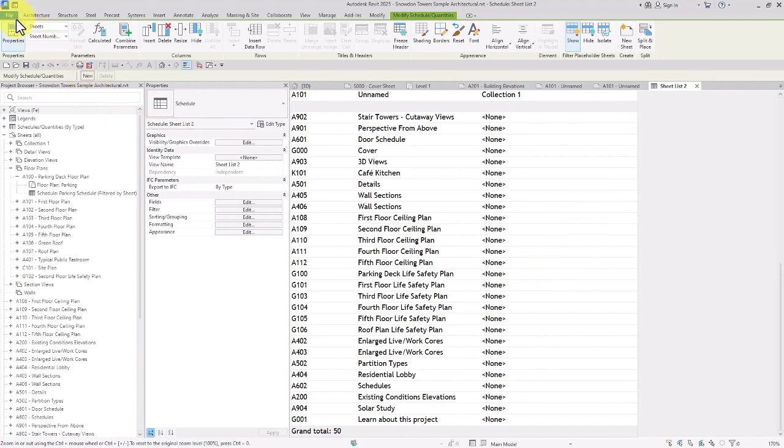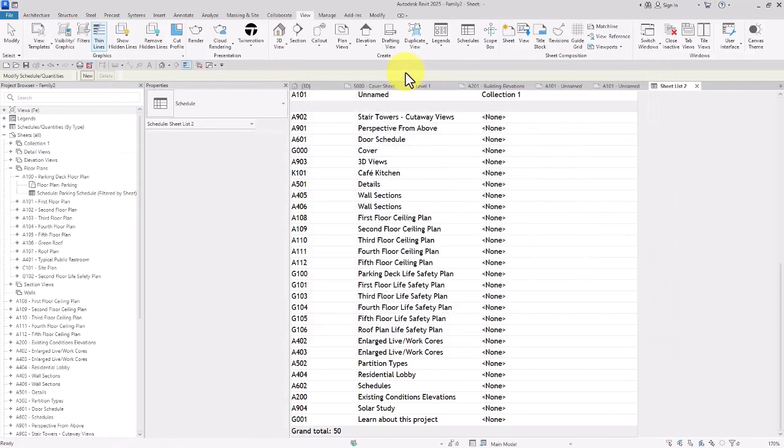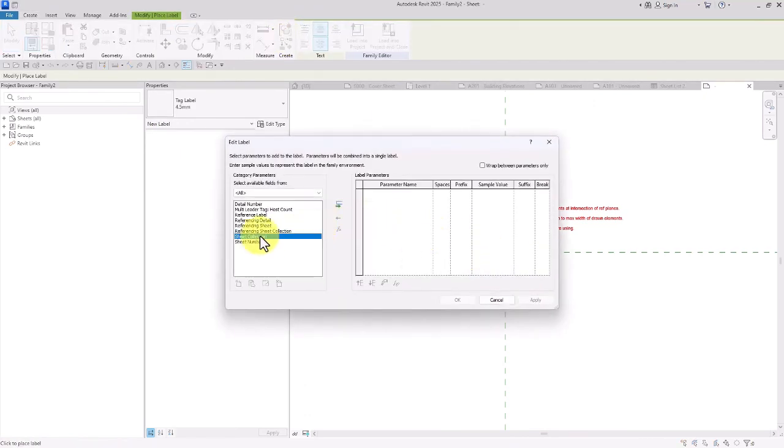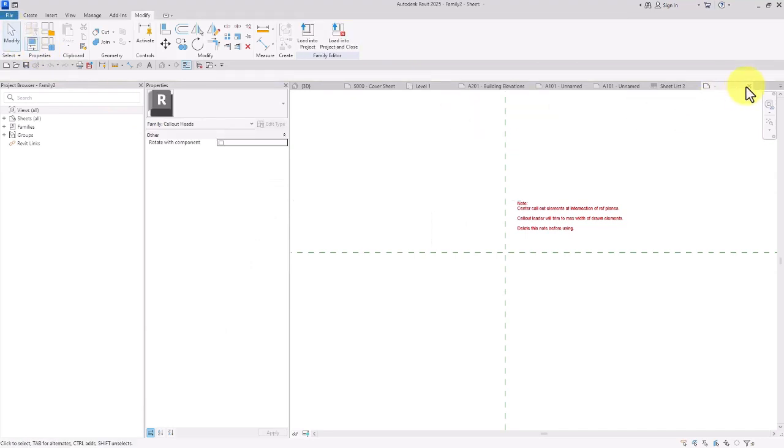All right, another point is that when we are tagging the sheet collections or reference sheet collections for a view title, reference, callout head, elevation mark, section mark, or title block, we can use either sheet collection or reference sheet collection. For example, I'm going to open up Files, View, Annotation Symbol. Now I'm going to select Callout. Now from Label, I can go ahead and add the sheet collection. And again, this is a very useful point. Or as another example, let me close this down.